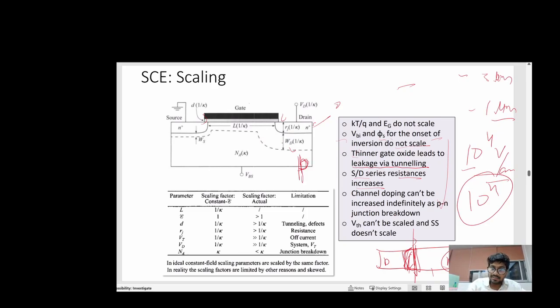That's why there is this depletion region width, right? This is the PN junction. In the previous class, I also told you why it should be P and it should be N plus, because whatever channel we are creating is an N channel, right? Yes, sir. So, sir, you say that WD will be reduced in this one if you increase the doping in this N plus.